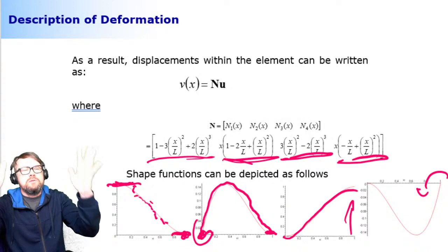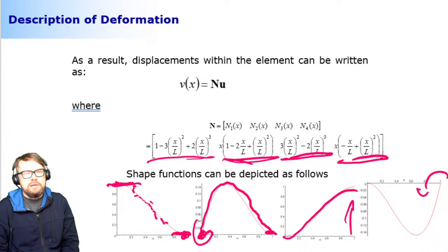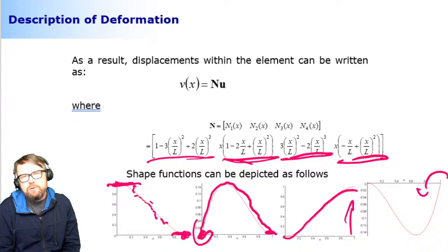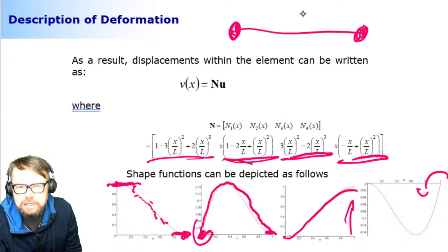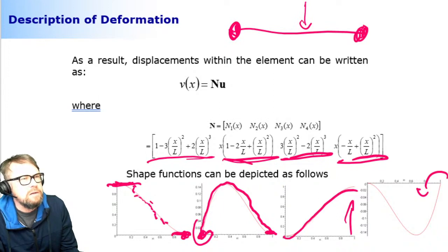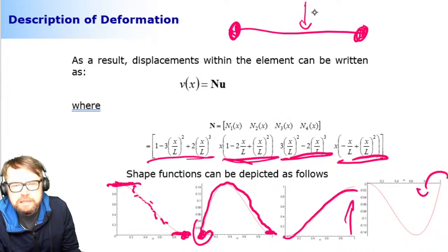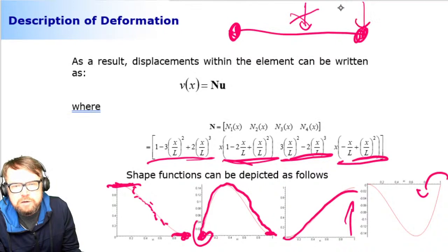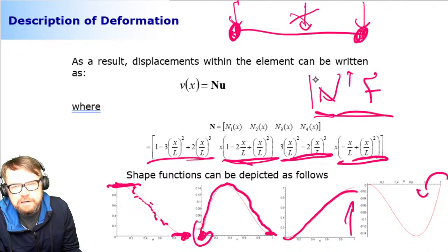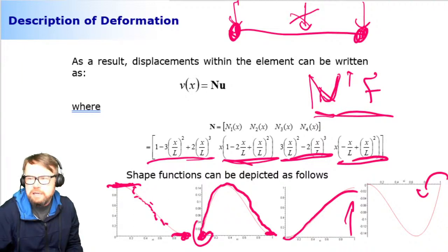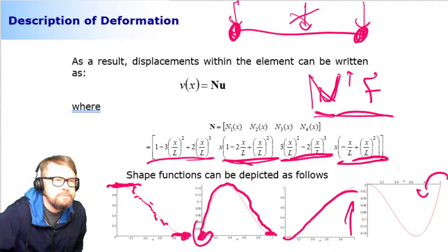And this is what I'm going to use, my shape functions, to build my stiffness matrix. I can also express my forces using shape functions. If you have a structure like this, where there are two nodes at both ends and the force is applied somewhere here in the middle, you can divide this force, which you cannot put in the middle, to nodal degrees of freedom with the help of shape functions. And it's going to be simple like this. Excuse me. So this is my shape function matrix multiplied by force. And there is a comment. So let me take a look at the comment.